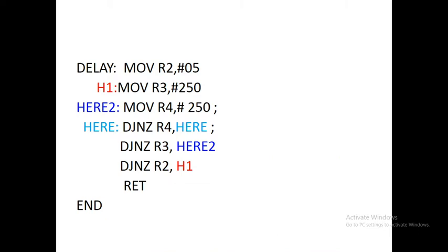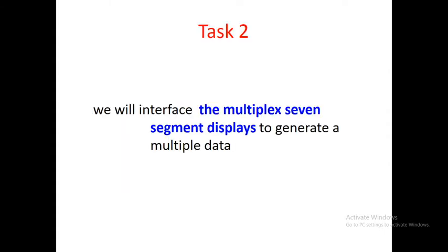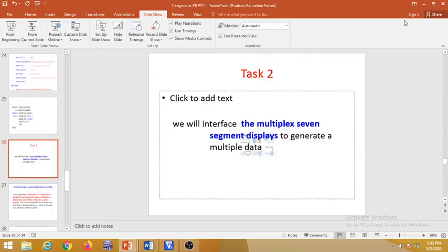Now you just call the delay, write delay subroutine. Delay subroutine you can write by the two ways, either for loop or timer loop. Here we are using the for loop. I'm just placing the count, and I'm just keeping in loop till it does not become 0 to introduce that much delay. Okay, now this is your first problem statement. Now according to that I will show the demonstration of that.